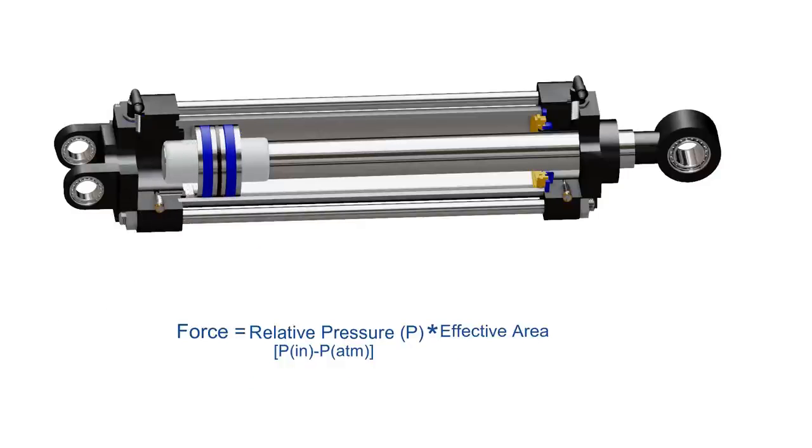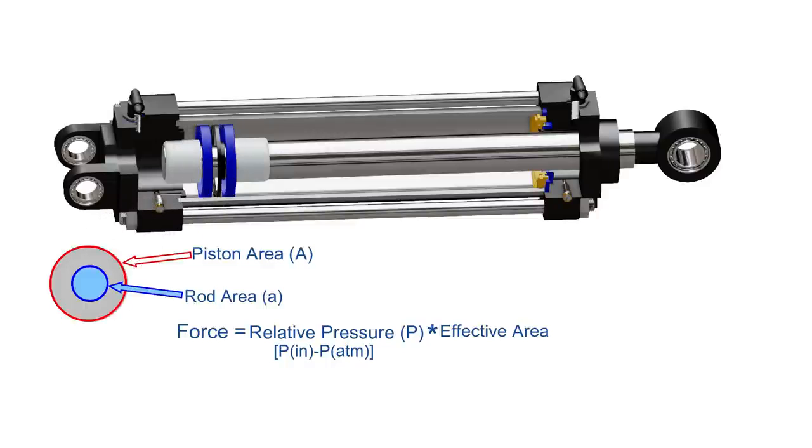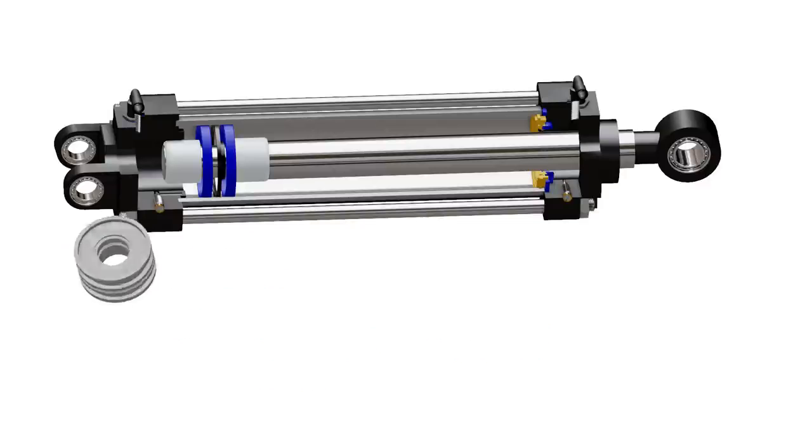During retraction, the effective area of piston is reduced because the air cannot exert pressure on the area of rod. This gives us the expression of theoretical force as relative pressure multiplied by partial area of piston. Frictional losses on the interface of different surfaces also needs to be considered while designing pneumatic cylinder. The diameter of rod and length of stroke is also a determining factor for capacity of actuator.